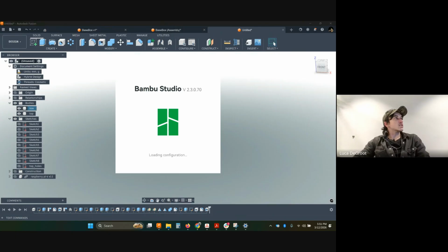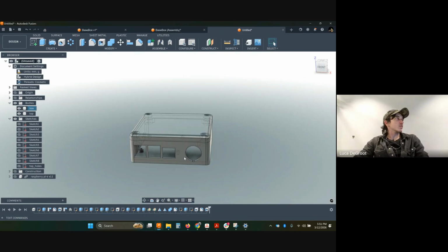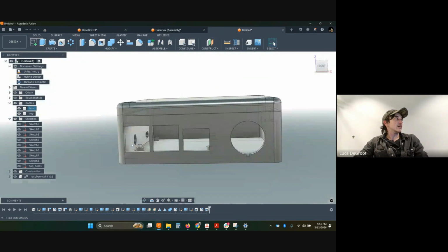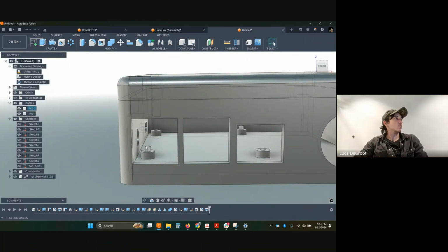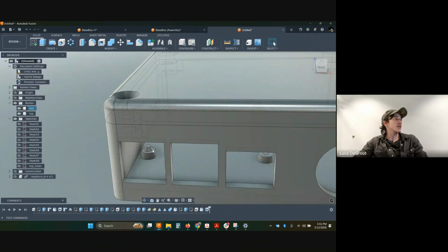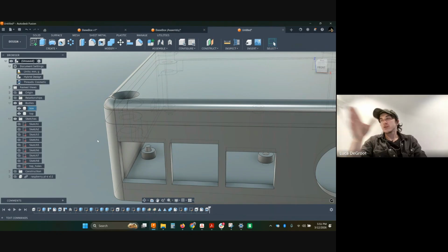Now, with regards to designing for 3D printing, the considerations are often your wall thicknesses and how close your fidelity might be. Sometimes if I'm doing really small parts, I'll design around my nozzle thickness. If I know my nozzle is probably 0.4, maybe 0.6, I might make the smallest feature 0.8, just so I know there's at least two walls, or 1.2.